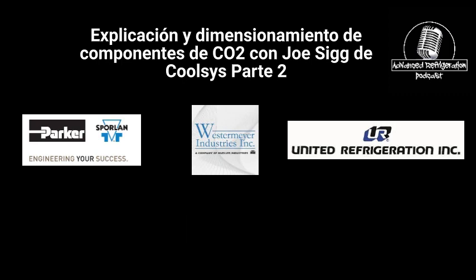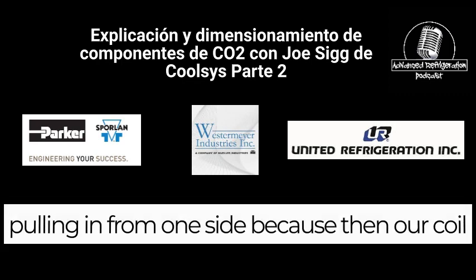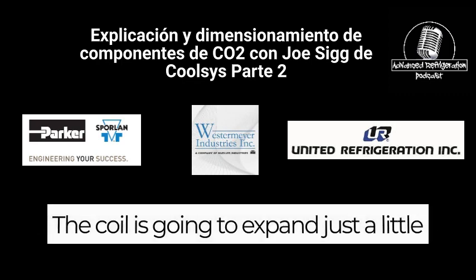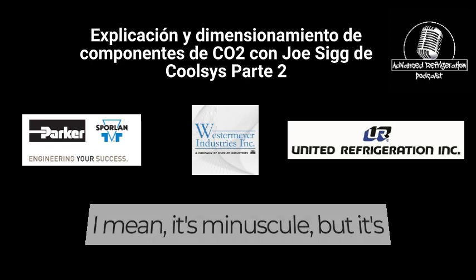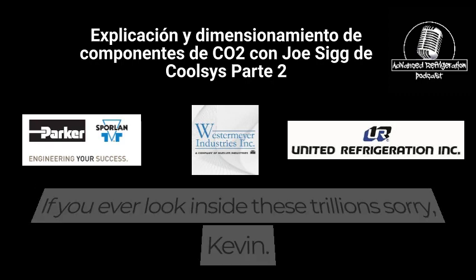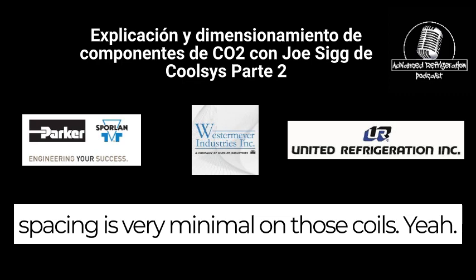How so? Because the system is expecting airflow coming in from two sides. And the fans will pull harder when it's pulling in from one side because that other coil's dead and there's no heat. Oh, so the coil is going to expand just a little bit, which is going to cause a little bit more restriction than it would, right? I mean, it's minuscule, but it's still enough to affect the airflow. If you ever look inside these Trilliums, you're going to see that the fin spacing is very minimal on those coils.